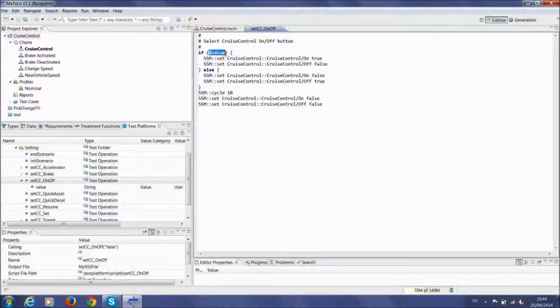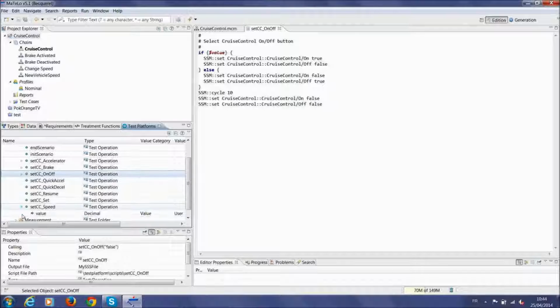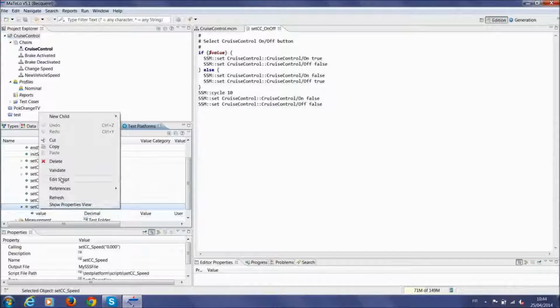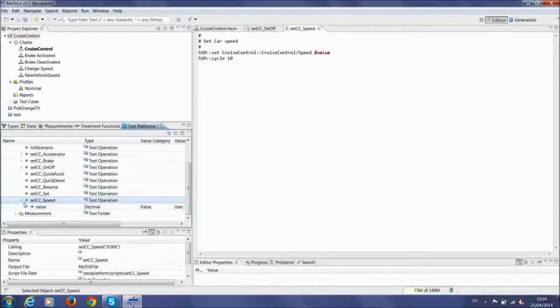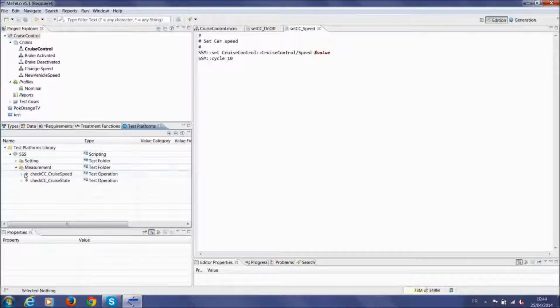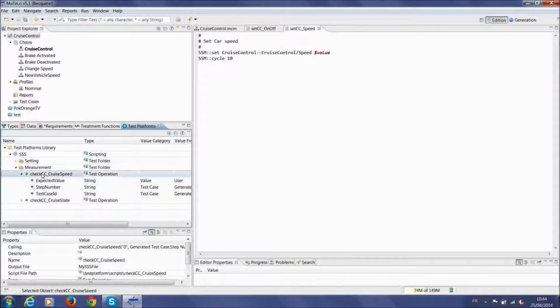The Test Platform tab contains the test functions to create your simulation environment. It is mainly a text field that you can edit in MaTeLo via a specific window. You can create or import your test script functions in any language of test you wish to use, from the moment it is editable literally. To visualize or modify the content of these scripts, select the function, right-click on it and then choose Edit Script.